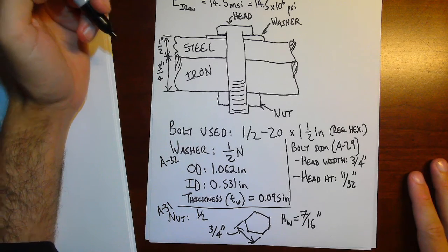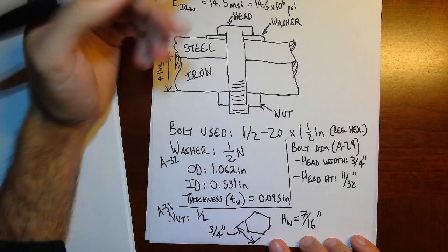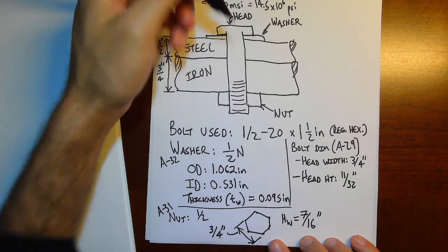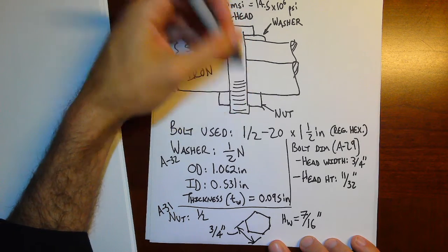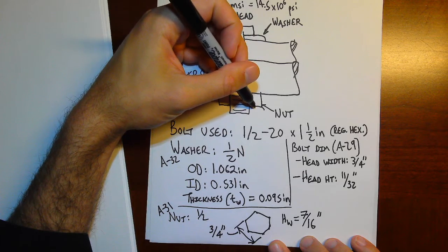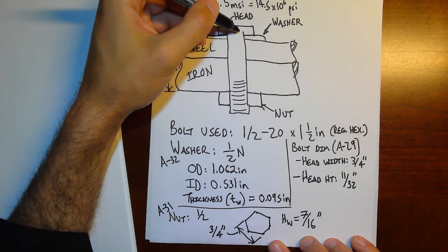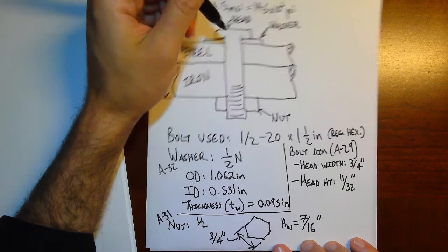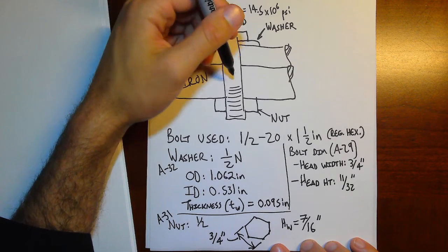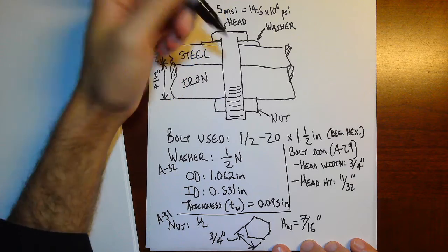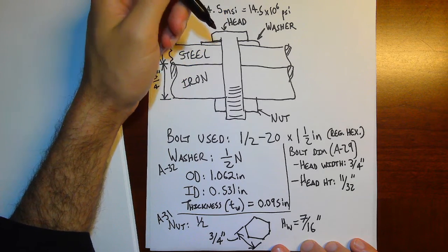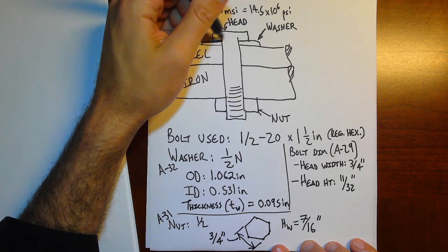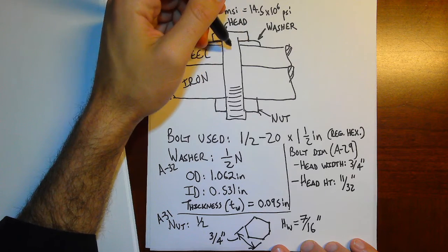So where to from here? So first question is, what's putting this joint into compression? So you have this bolt, you have the nut on one side, you have the head on the other. If I think of this joint as I slide the bolt into the joint, it's still not in compression, but it's being held on one side by the head of the bolt, right?